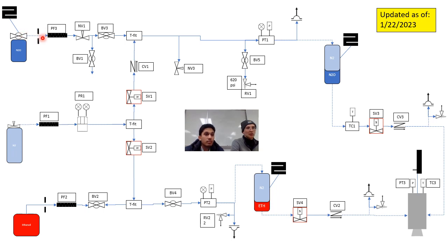Naturally, some people might want to just unscrew it at that point, but what would happen is as you're unscrewing it, you might just pop it off as it gets to the last thread. 900 psi, not good. So what we want instead is some kind of valve, a ball valve, whatever is the cheapest and still somewhat safe, just a way to use a valve to open and release that 900 psi and lose some of that nitrous oxide inevitably. But as long as that ball valve on the bottle is closed and BV3 is closed, this will vent